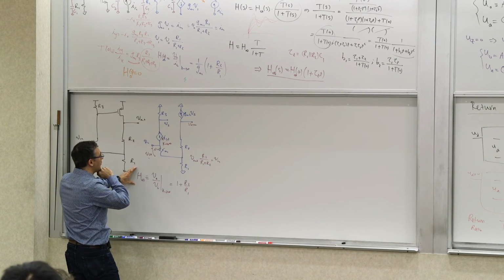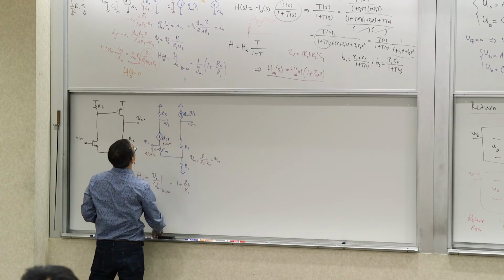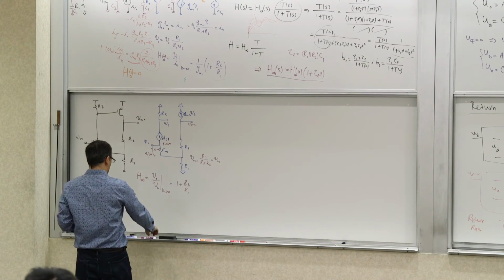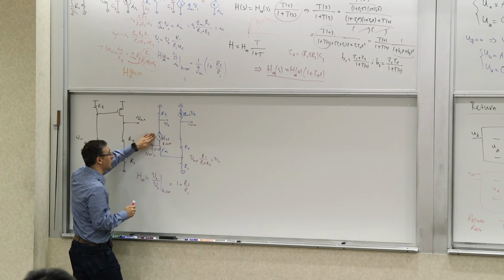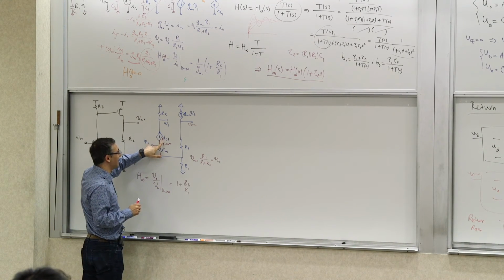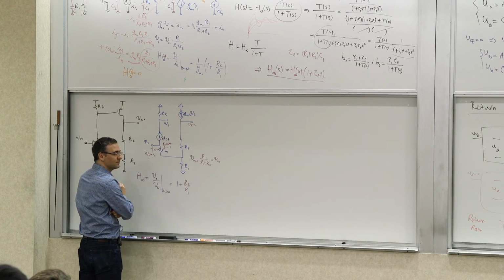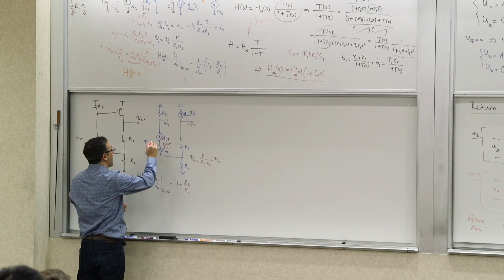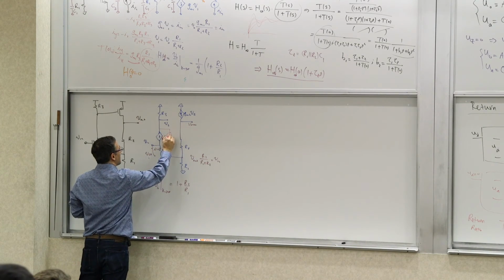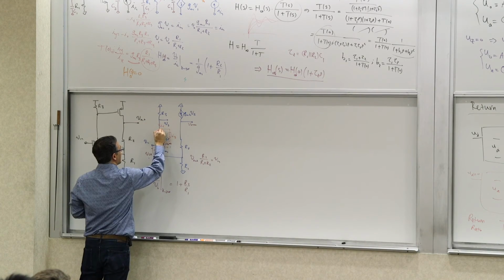Now, what else do we have to calculate? We have to calculate the return ratio. For return ratio calculations, we picked our source and we cannot change it. So we are going to say that now k is 1 for the return ratio. So for return ratio, k is 1. And then we are introducing this source. So this is Iz, this is Ix, and this is Iy.